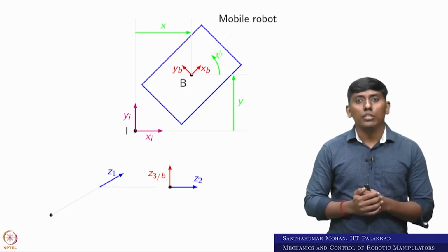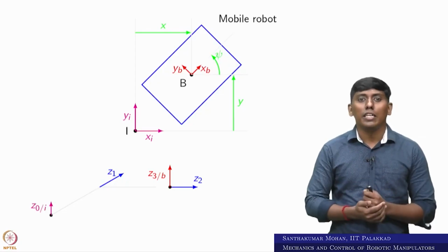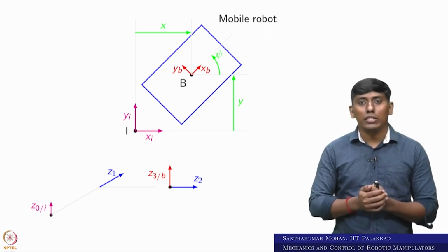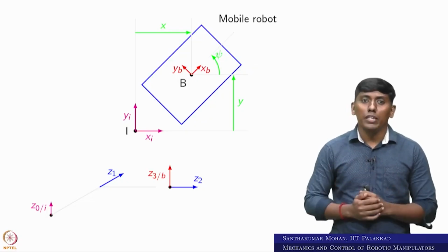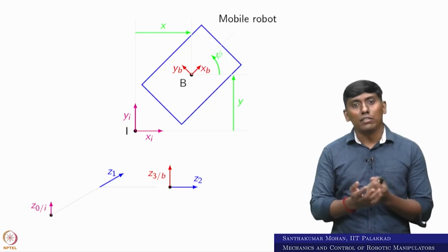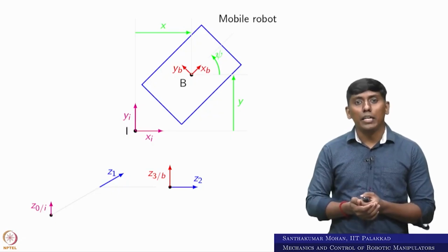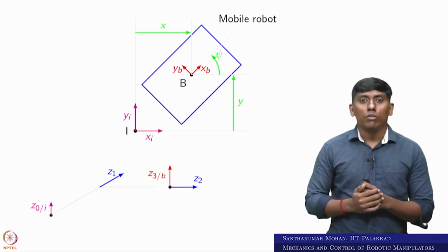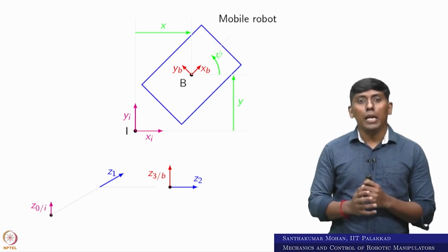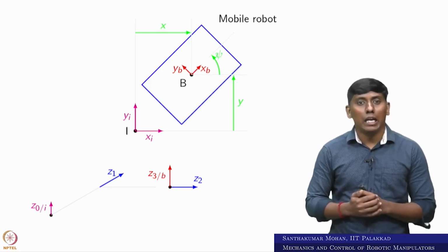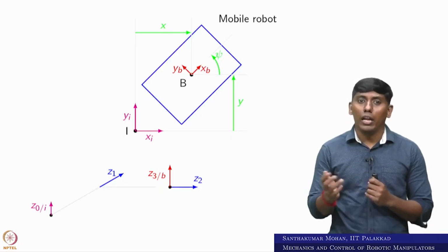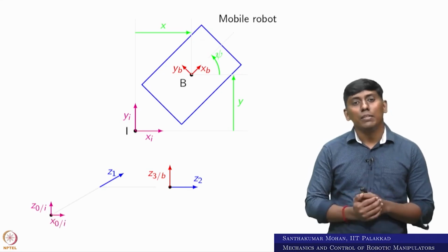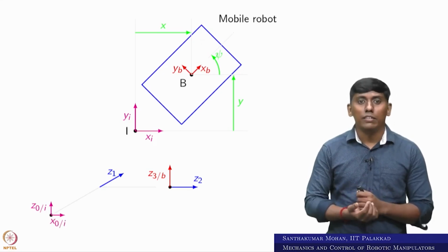Now what I am trying to see is, from the initial frame, how it goes from one to another. So now I want to derive it with the Denavit-Hartenberg approach. For that, what do we need to know? You need to know where the x-axis comes. The first x-axis, which is x0, can be written this way, perpendicular to the plane containing z0 and z1. This is what we learned, right? So in that case you can draw this line, which is the plane containing them. In that sense, this is the forward direction of x0.